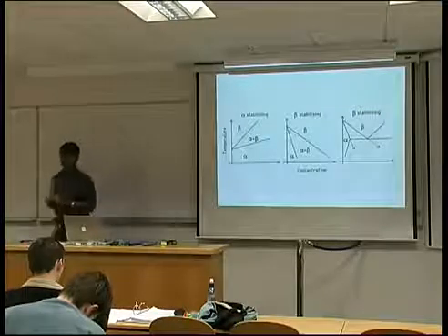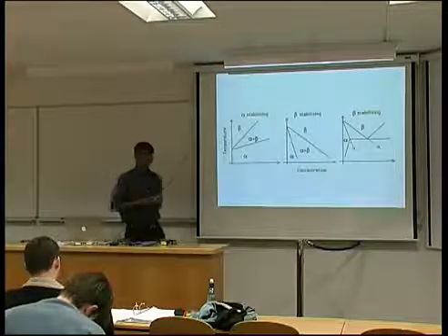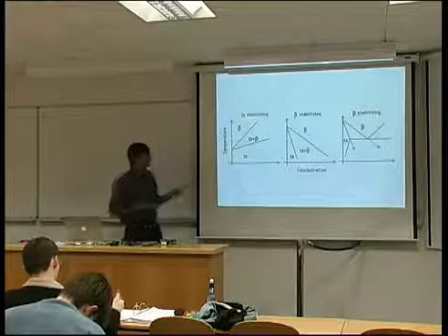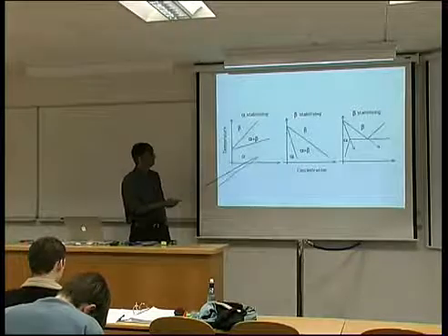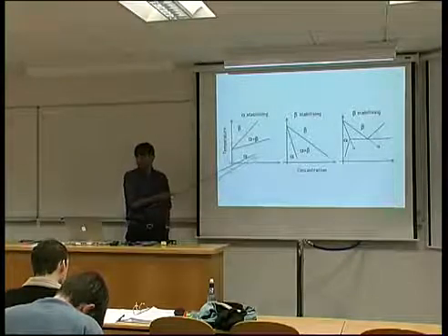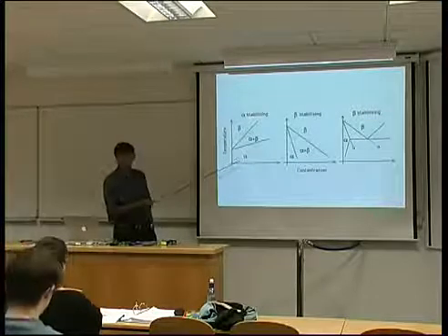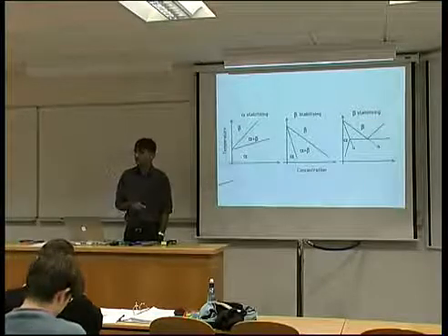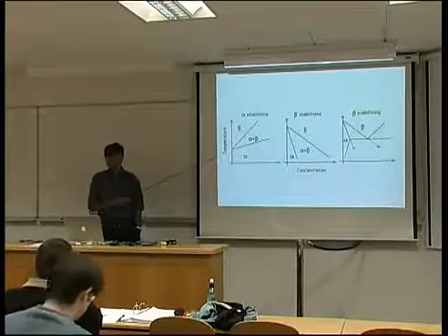These are the typical sorts of phase diagrams for titanium alloys, and they have some obvious labels. This kind of phase diagram is when we add solute, you increase the extent of the alpha or hexagonal close packed phase field. Elements which do that, for example aluminium, are known as the alpha stabilizing elements.